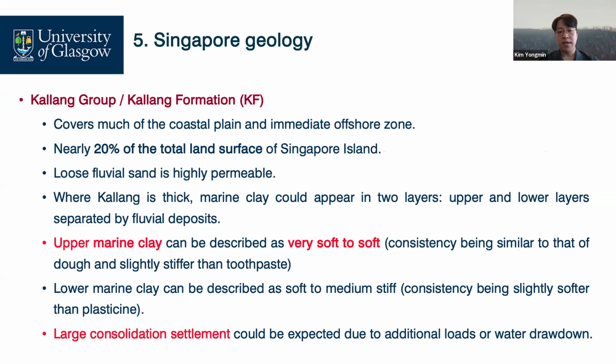So I'd like to highlight that the upper marine clay can be regarded as very soft to soft clay. It's similar to Play-Doh, slightly stiffer than toothpaste. It sounds like a very weak layer, right?